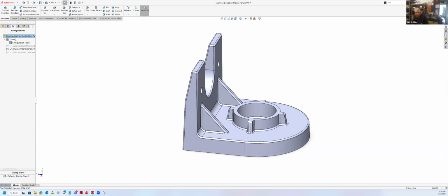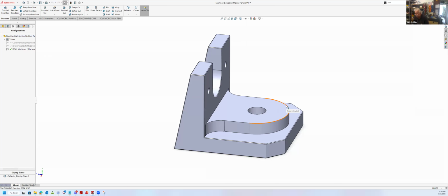So in the beginning, he mentioned that on the edge break he was considering just throwing that in a tumbler and tumbling it, but he actually modeled an edge break on the part. When you do that, if you go into your software for the deburring function or the chamfer function, it's going to want a square corner there for you to pick for your tool path because it's based off that square corner.